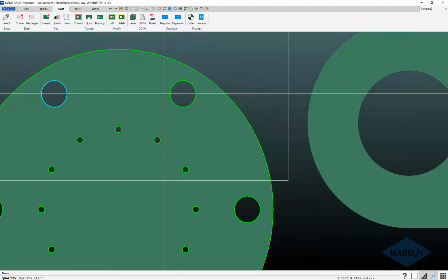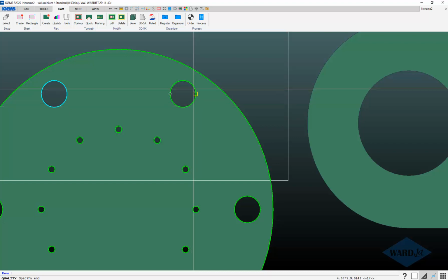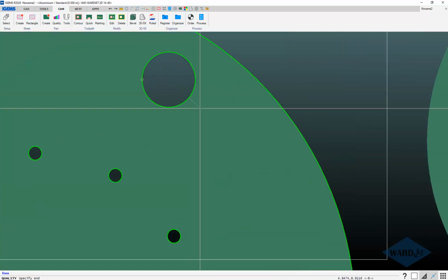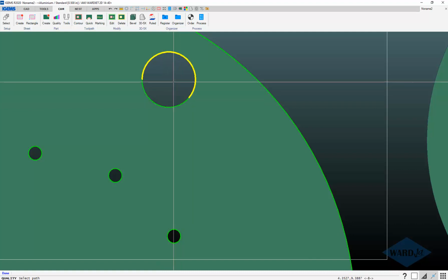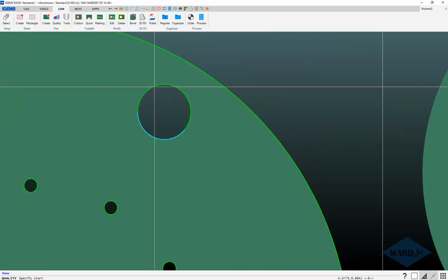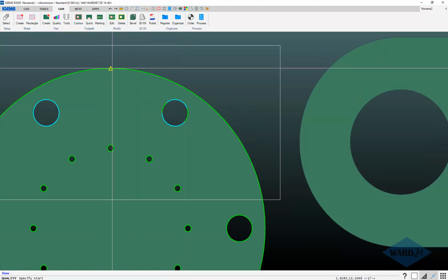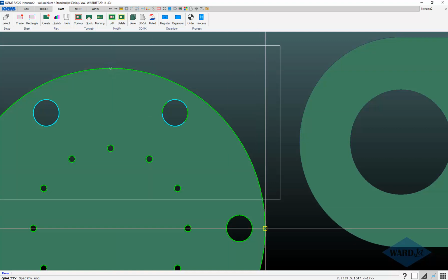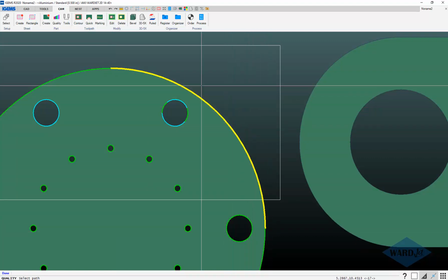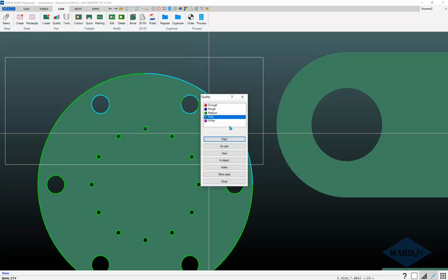If you want to just do that for a portion of a cut, you can basically left click one point and then left click another point, and you don't have to be right at one of the snap points. It can be anywhere in between, wherever you want. So I left click again and then I hover my mouse, and if I want this portion to have that quality applied to it, then I left click and lock that in there. So just left click, and left click. Since I do have my snaps on, if I want to be more particular about it, so if I want to go from this snap point here to this snap point down here, once those snap points show up, I can just left click and lock those in there. So that's the paint command.